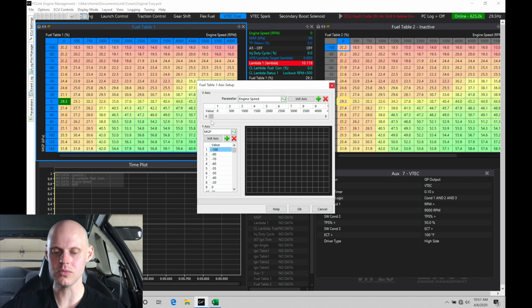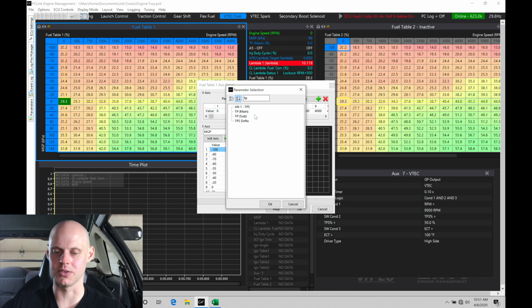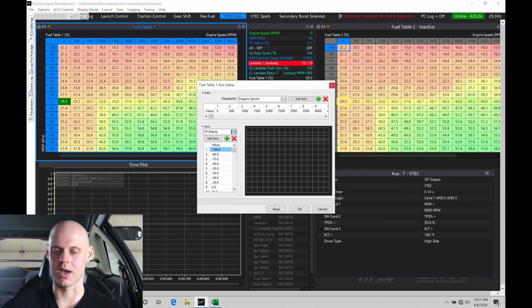That's fine. On our y-axis here, we want to do this based on TP main, or throttle position main. That's going to allow us to do alpha-N style tuning. Let's do TP main. Let's click OK. Now we're going to get rid of...